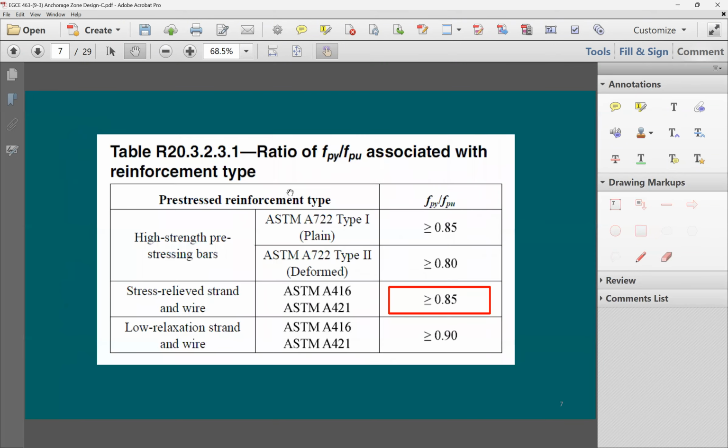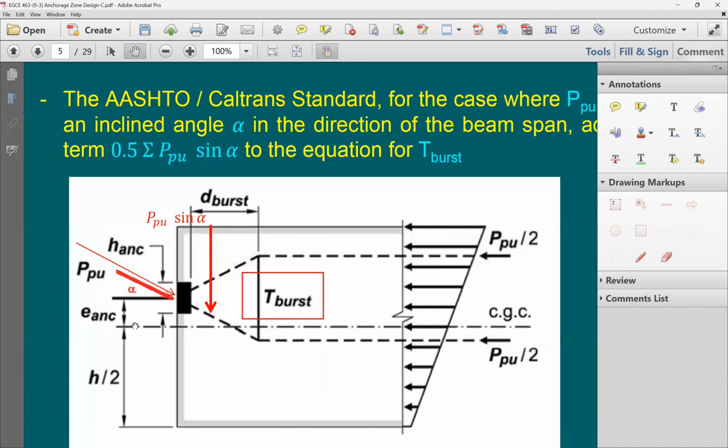I'm going to go back here to one of these pictures. The contact area between the plate and the concrete is not the total area that would see all the compression force. Example: if I take this area here, right? You're going to say, put a plate with this total height. So the area of the plate is going to be the same as the cross-section area of the entire beam.